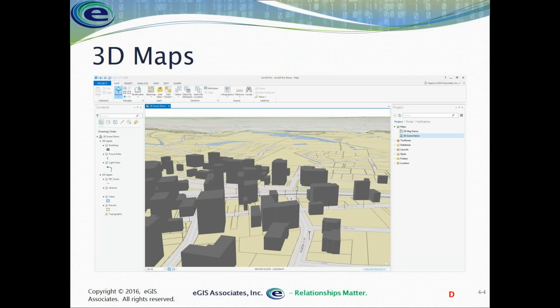Okay. So, as I mentioned, ArcGIS Pro has the ability to create 3D maps without the need of an extension. In the days of Arc Desktop with ArcMap and ArcCatalog, we actually had to have an extension. We had to have 3D Analyst in order to produce 3D maps. And that's because 3D Analyst came with two other applications, being ArcScene and ArcGlobe. And within those two apps, we could generate these 3D scenes for seeing different 3D relationships, extrude buildings up, and all those kinds of things.